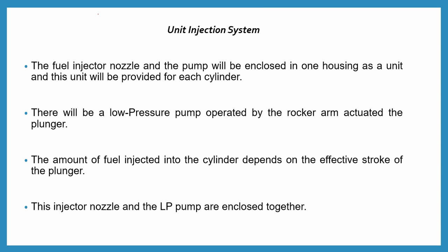Here, the amount of fuel injected into the cylinder totally depends on the effective stroke of the plunger. The injector nozzle and the low pressure pump are enclosed together.